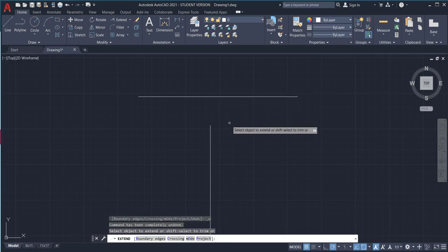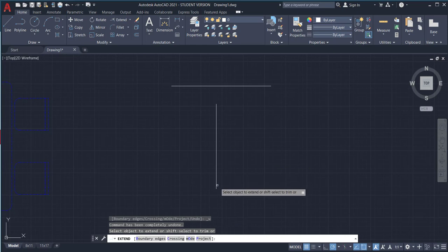Now I'm curious to know if I clicked on it on this direction, yes. See how it ghosts it up here? But if I try to click on it while I'm down here, it does nothing. So you have to click in the area closest to where you're trying to extend the line. That's where the smart part of AutoCAD comes in. Click and you've extended.